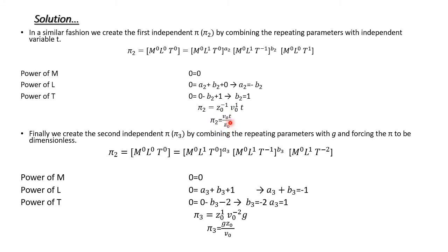You just go back and check the dimensionless terms that we got. z star is equal to z by z0, so that we got as the pi 1 term, and one more term we had got as t star is equal to v naught t by z naught. So look here, pi 2 is equal to v naught t by z naught. That is the beauty of dimensional analysis. Similarly, it is pi 3, not pi 2.